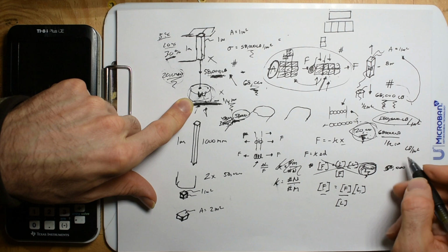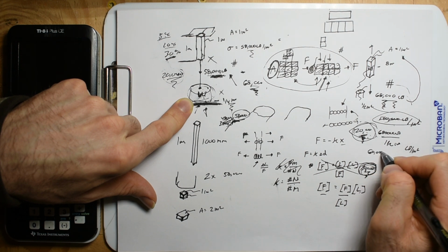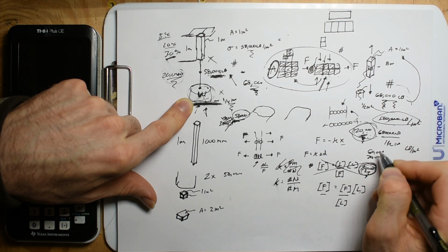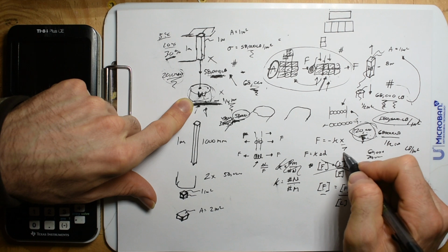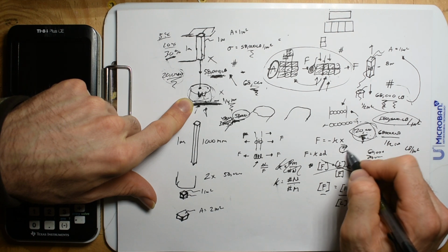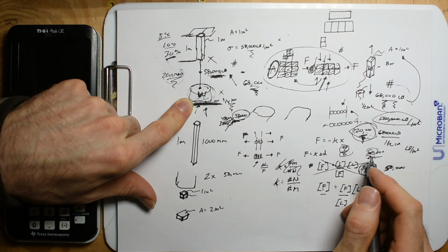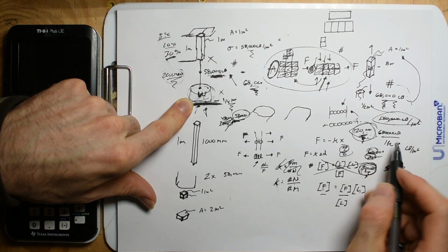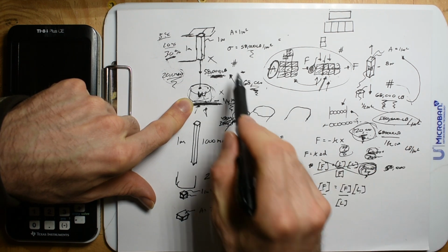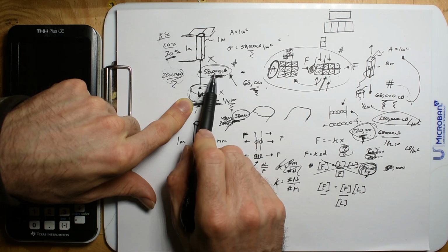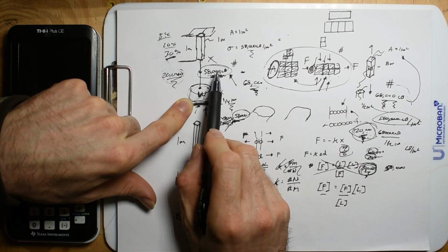Should be 50. When you weld, it's either going to be 60 or 70,000. That's because you have like 60-10, 70-14, whatever. That 7 indicates 70,000. That 6 indicates 60,000. So even just welding, you're expecting 60 to 70. So 58's not a bad number to assume.